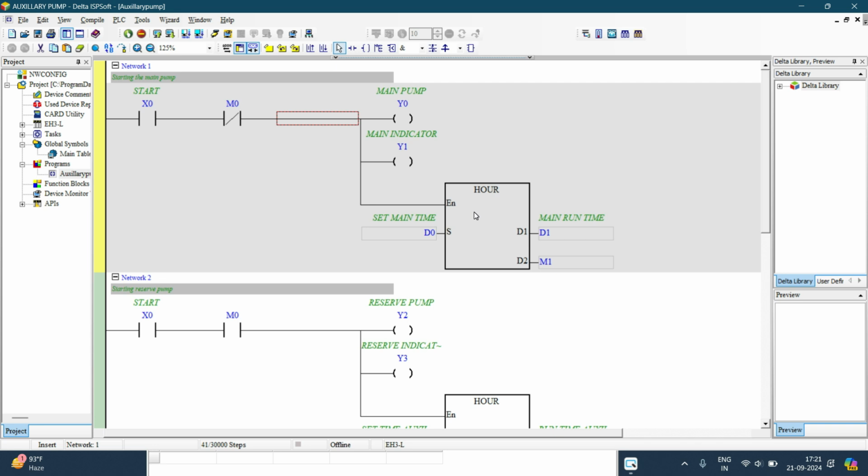If you put 5 hours, this command is going to raise a signal over here because it has two inputs. It has the time you set, that is in D0, because in D0 we are going to store the time you set. And in D1, if 1 hour passes, we are going to find here 1, 2 hours, we are going to find there 2. But when this one meets this, like if you put 7 and here there is 7, this signal will go high. Whenever this signal goes high, we want it to go to one of our internal relays. So this one is set high.